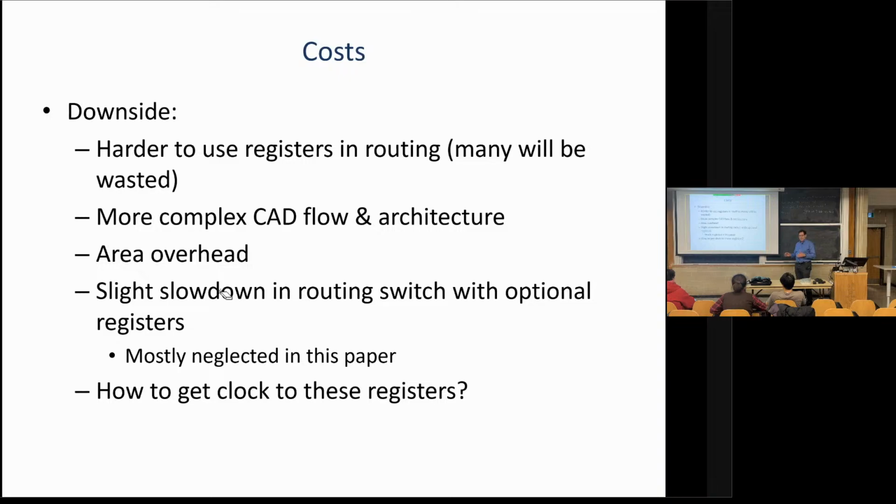Does that make sense? And they are also harder to use because, skipping ahead to what they did, to keep the cost down, they built simple registers. Simple registers don't have clock enable, synchronous clear, asynchronous clear, etc. So they are somewhat harder to use, because if you have those extra signals on your register, the routing ones are simpler and they can't do it. And then they have CAD techniques to say, well, maybe we can redesign your logic in front of the register so you don't need a clock enable anymore. And sometimes you can, and sometimes you can't. Does that make sense? Yeah.